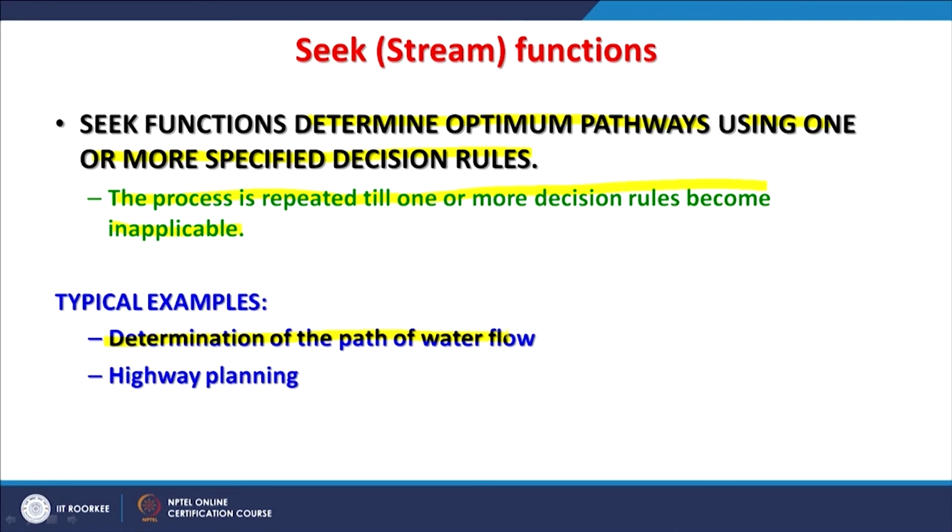So, using a digital elevation model, one can determine even a drainage network, and sometimes a very accurate drainage network or stream network you can do. Once the stream network is there, then a person who works in hydrology will ask, can you develop a stream ordering, which are the first order streams, second order, third order, based on two very popular schemes, one is Strahler and Shreve, and you say yes, I can do it.